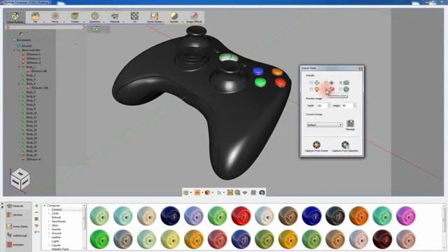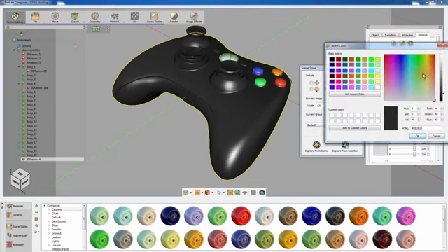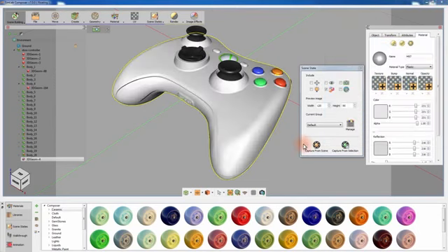To capture the material attribute, disable the camera's attribute and enable the materials attribute from the Scene State Manager and then click Capture. Now that you've captured the materials in the scene into a scene state, you can modify the object's appearance by adjusting the material's color, for example, and then clicking Capture Scene States again.